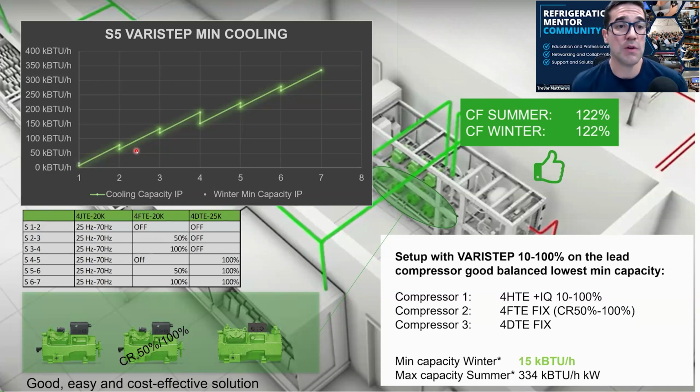So that's something you want to talk about with your customer, or if you're a designer or engineering firm out there, you want to have a good understanding. And most do today. Most manufacturers I work with are real smart, so they understand the differences. But that's something you should think about with any rack or any parallel system. Why did they put this many compressors here? What is the capacity of it? And the biggest thing is the gaps as well.